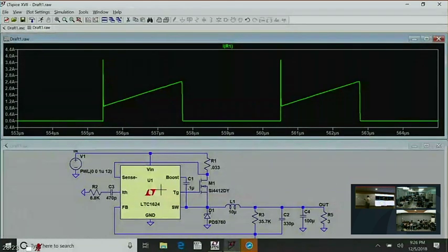Basically, it's stuff like this. That's why you use controllers. You base your switch mode power supplies on dedicated controller ICs instead of 555 timers because they're deglitched with junk like this in it. This high-speed blanking is very effective for the spike because the spike is very well isolated in time and not frequency, so it works great for that.